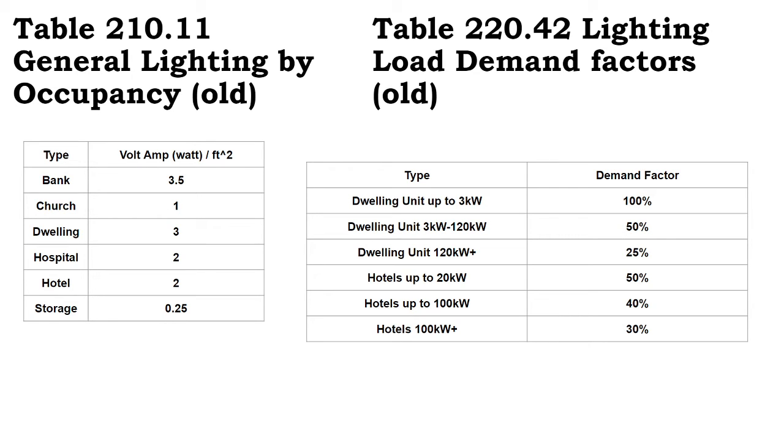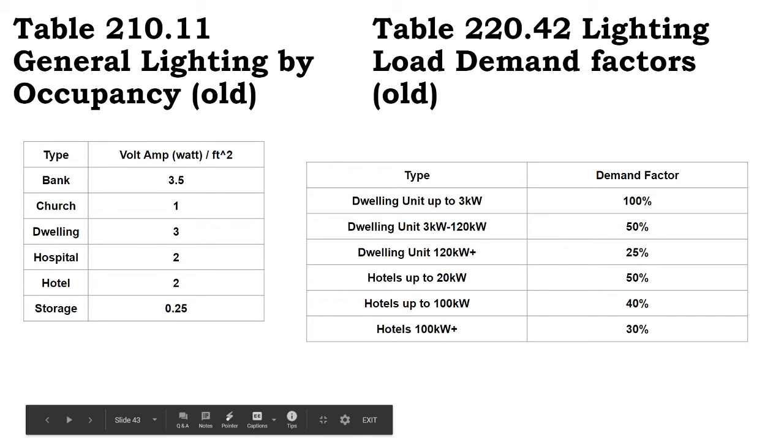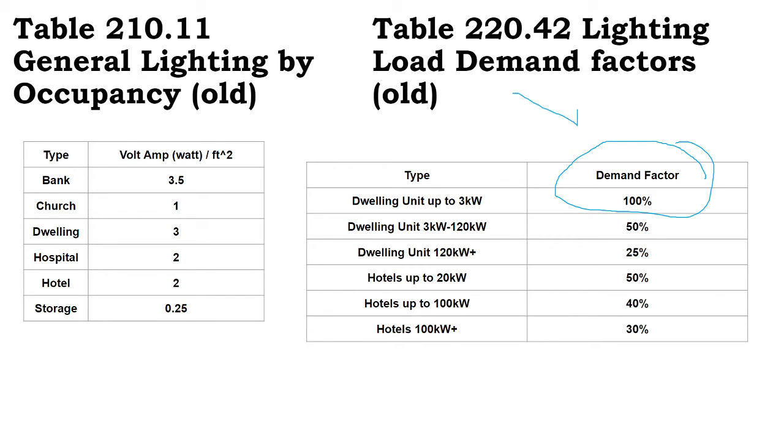As far as determining how much power should apply to a house, there are load calculations. So what do you need to do? Well, for dwelling loads, this has changed a lot, right? Because LED lights are very different than incandescent lights. And so one of the major changes to code for 2020 has been a reduction of the load calculations. What we can see here is that you might calculate all the demand for a building and you don't get any deduction.